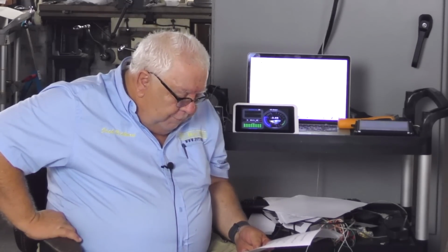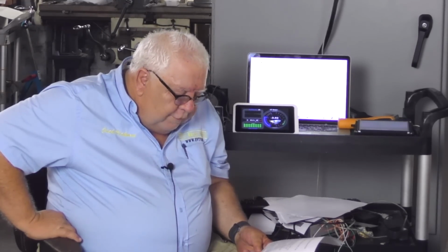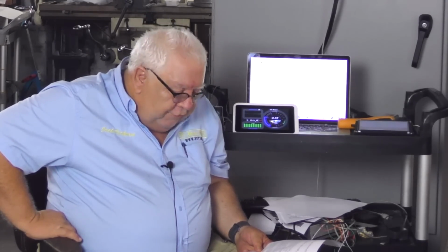That enabled a number of further calculations. Of course, power in watts was defined by James Watt. He also gave us horsepower. But if you multiply the voltage times the current, voltage in volts and the current in amps, you'll get power in watts. So 1 volt times 10 amps would be 10 watts, or 10 volts at 1 amp would also be 10 watts. And that relationship is kind of important.